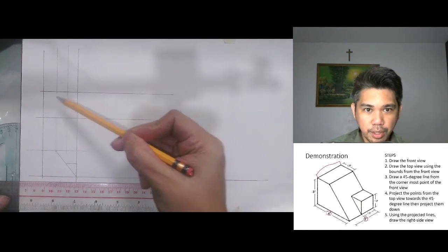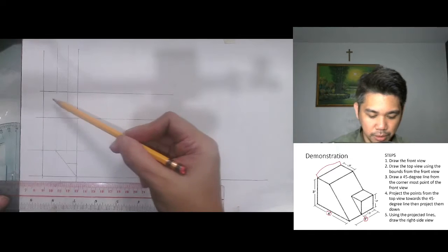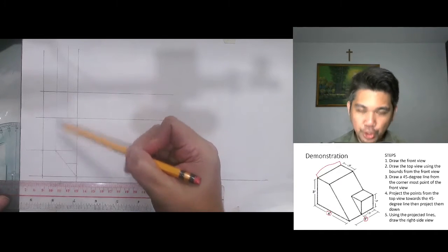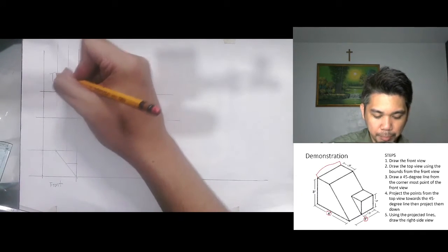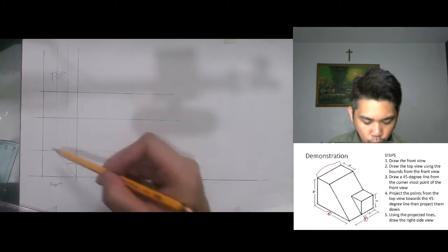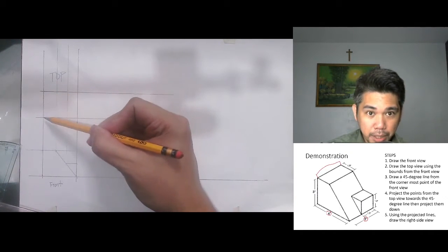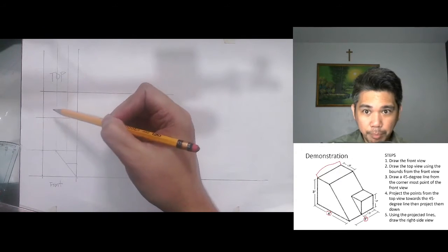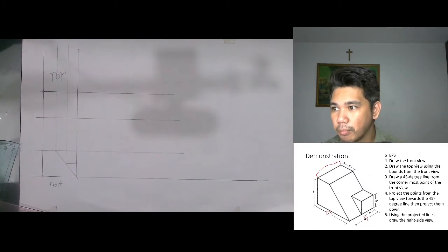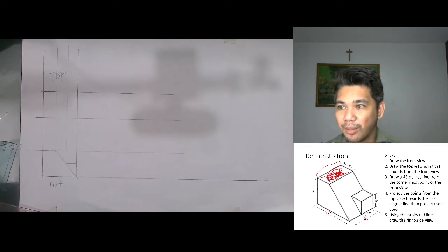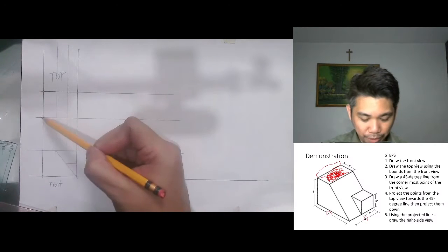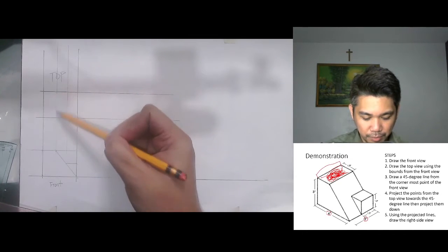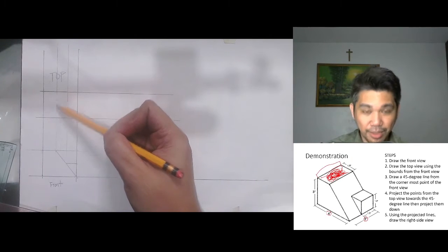So there is a rectangular figure here. Now, since we've projected lines from the front view to the top, I will write here top because this is the top view. Look at this rectangular piece. This rectangular piece, I'm going to the slides, is actually this one. Okay? What is this width? It's 1.5. What is the length? It's 3 inches.